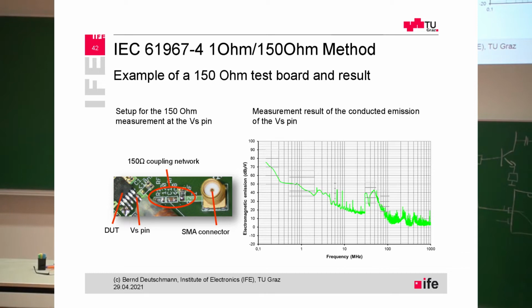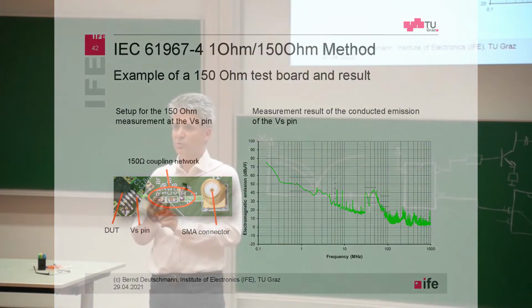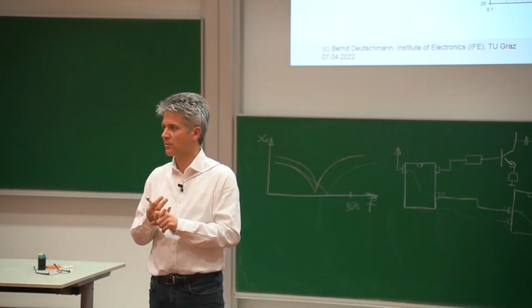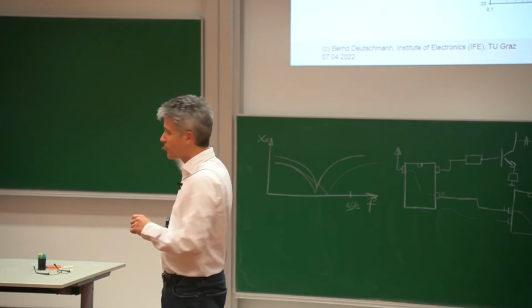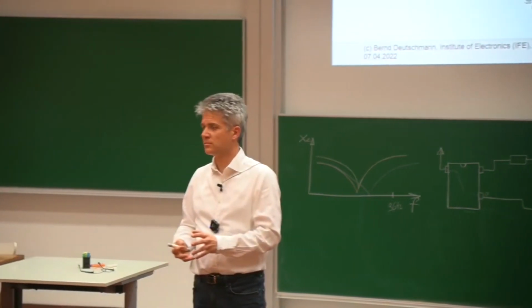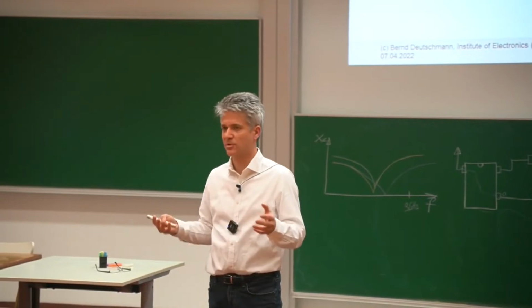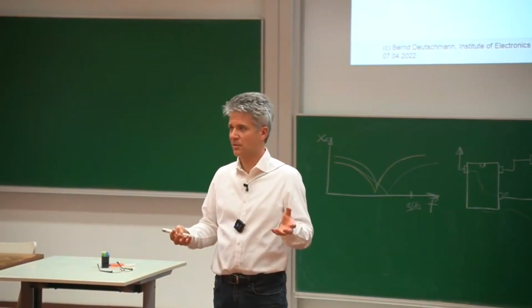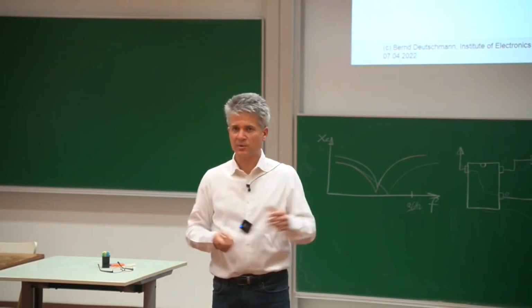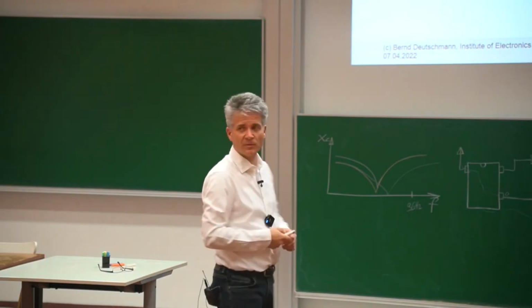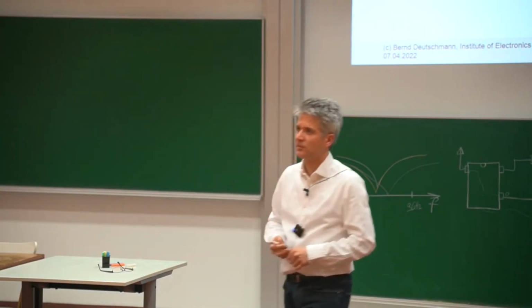so slightly you can see some limits here, and also here. These are the frequency ranges for the long wave, middle wave, short wave radio reception. And there, the resolution bandwidth is 9 kilohertz, or the separation of the channels had to be at least 9 kilohertz. So all this stuff comes from the radio reception, and now we can ask ourselves the question if it's still that important, because who is listening to AM or long wave or middle wave radio anymore? But still we have the regulations and also the limits here, so we have to fulfill these requirements to be below the limits.